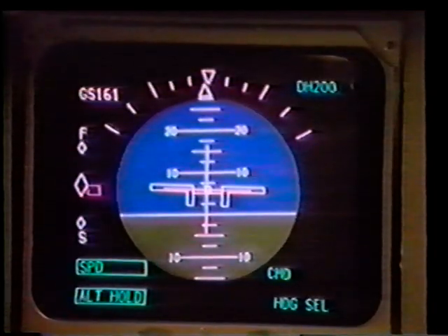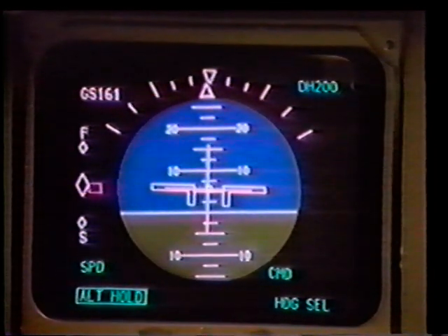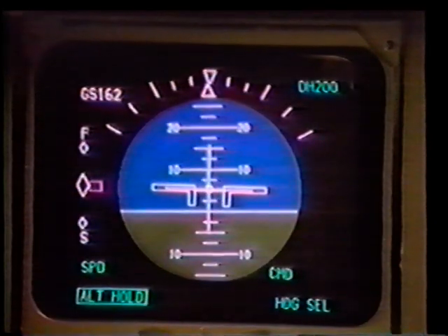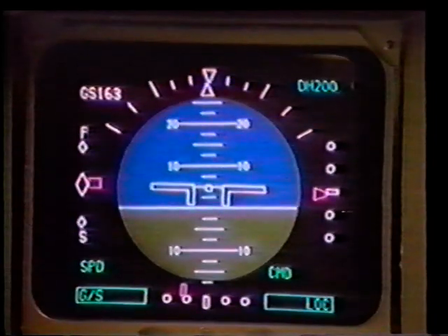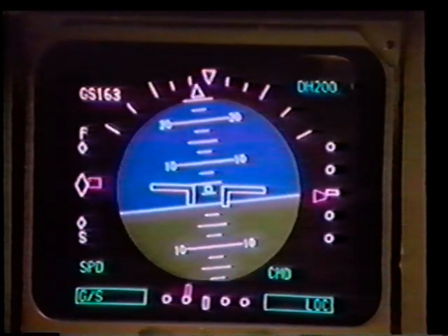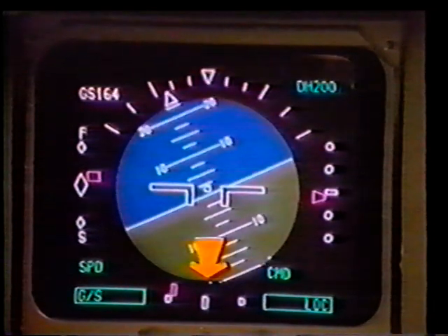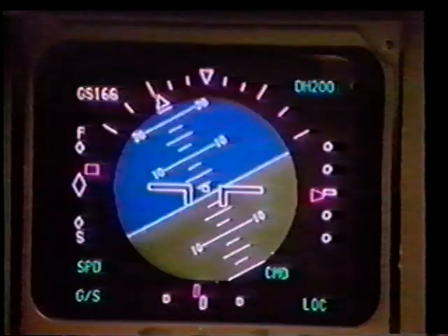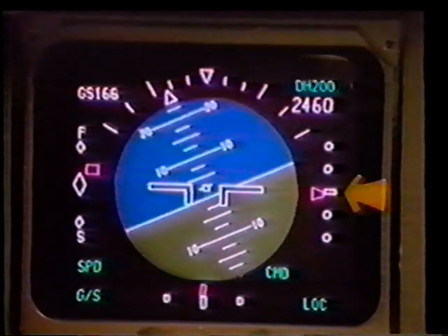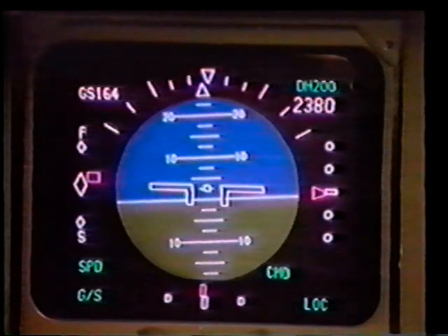Important auto throttle and autopilot flight director mode changes are emphasized for 10 seconds by a green box appearing around the changed mode. Localizer and glide slope deviation scales may be selectively displayed by the pilot. After localizer capture, the localizer deviation scale automatically changes to an expanded presentation 4 times as sensitive as the standard deviation presentation. Glide slope deviation is shown on the right side scale.